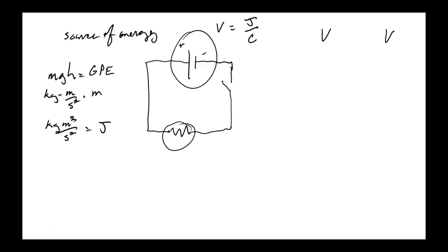So the zinc can receives the electrons, and the carbon gives up the electrons. So the carbon rod winds up being positively charged, the zinc can negatively charged, and in between that is that electrolyte. You'll see paper in there. That paper is soaked with a material that transmits the charges. Now, we call that a dry cell battery, but it has to be moist inside, otherwise it doesn't work.